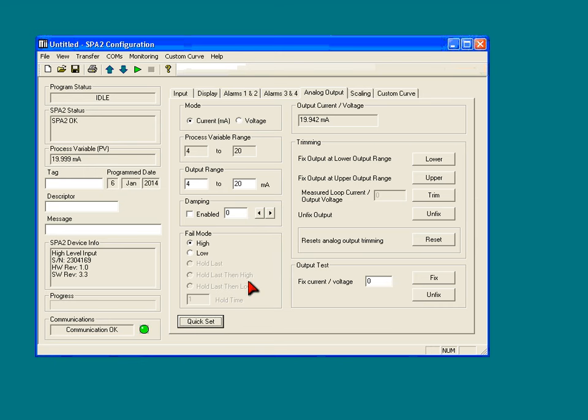There. And of course, if I start it back up, you'll see this will pop right up to 20 milliamps, the same as the input, because there's no longer any dampening. Before I take a reading, there we go. 19.999, close enough for government work. Okay, and we can also discuss these over here, which are good for maintenance purposes.